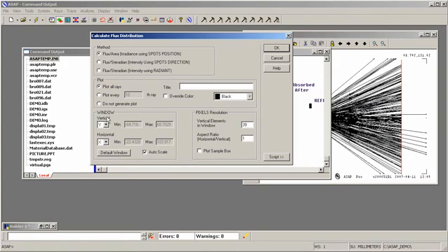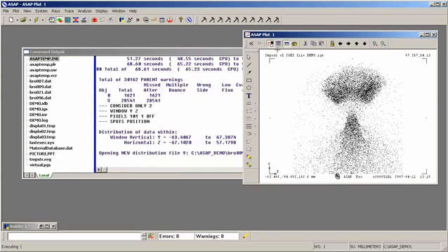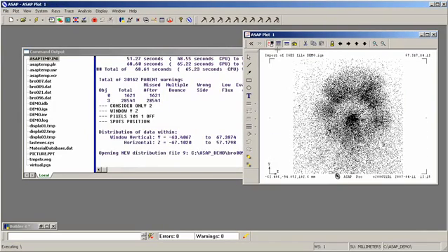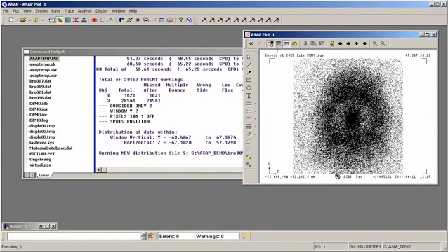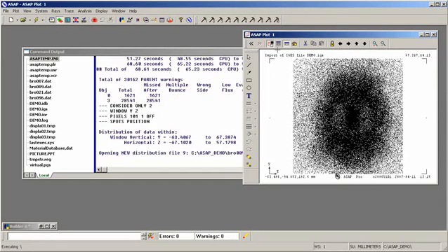Down here, the window axes, vertical Y is okay, horizontal will be Z, and finally pixel resolution for the irradiance calculation. In other words, how many pixels are aligned along the vertical axis of the window. I'll use 101 here, click OK. Initially, a spot diagram is displayed. At the same time this is being displayed, ASAP is recording the irradiance value at each pixel on the screen to a separate file. That information can be processed and viewed using the display tools.